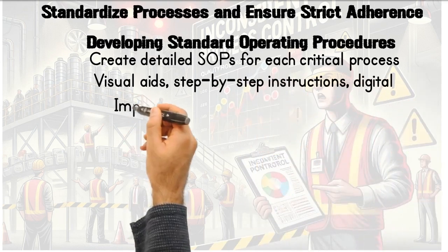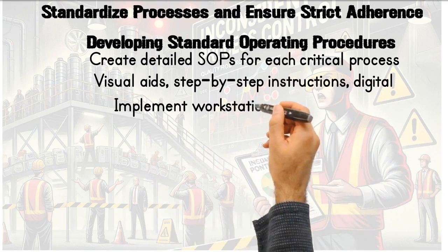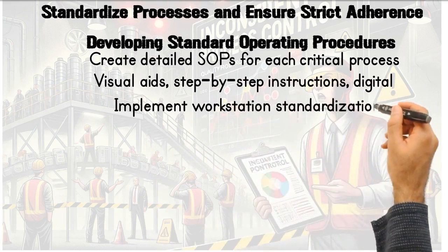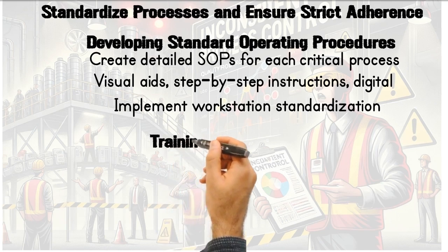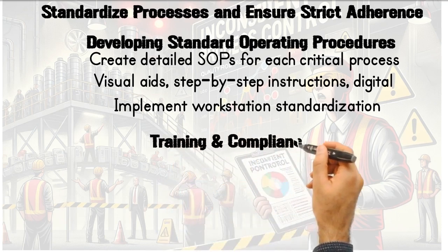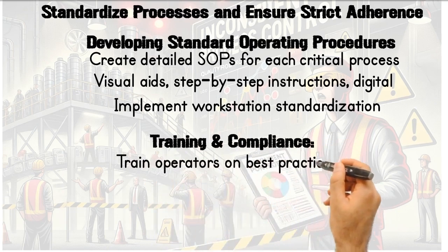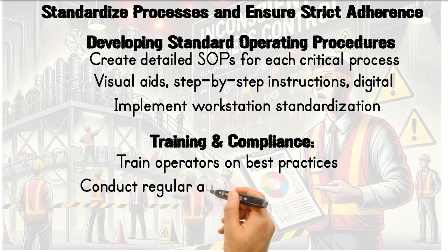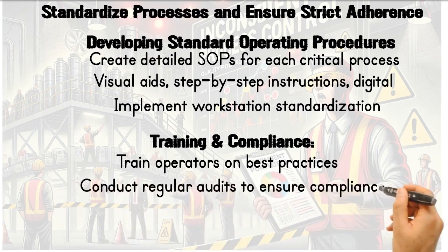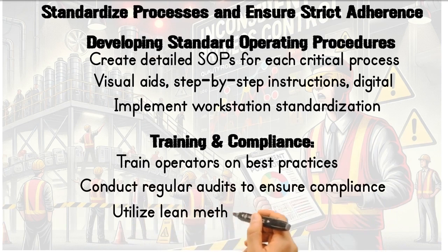Implement workstation standardization to reduce operator variability. Training and compliance is critical to get this in place. Train operators on best practices, SOP adherence, and quality expectations. Conduct regular audits to ensure compliance with standardized processes. Utilize lean methodologies such as 5S and Kaizen to sustain process consistency.